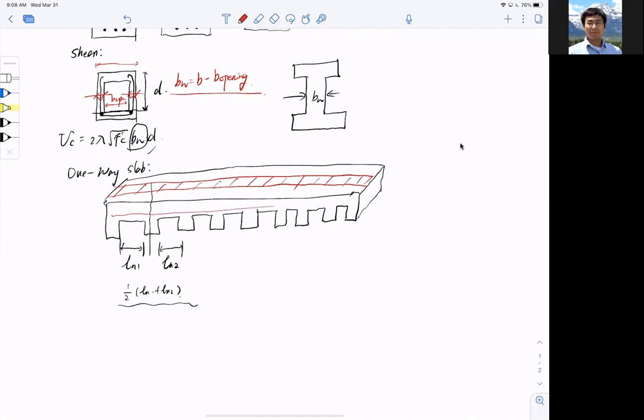The slab goes this way, and the reinforcement goes this way. This portion is not slab. Don't confuse yourself. This portion is the beam, the support underneath it, and the slab is going this way. For the reinforcement in the slab, be mindful that when you design for this slab, everything is per foot. We will have a problem where you need to combine the knowledge of the moment coefficient, the coefficient of moment, and design this.